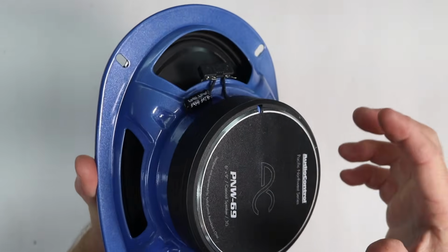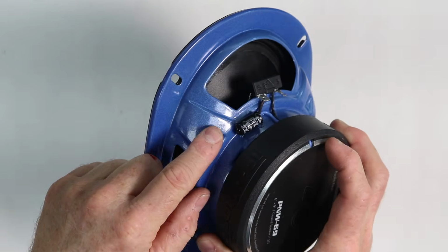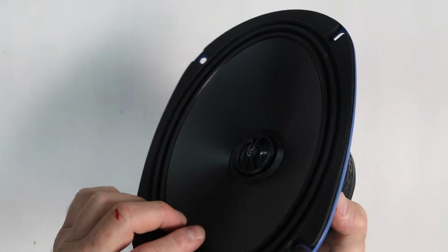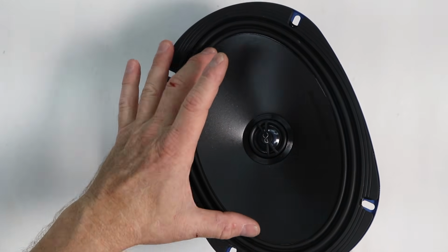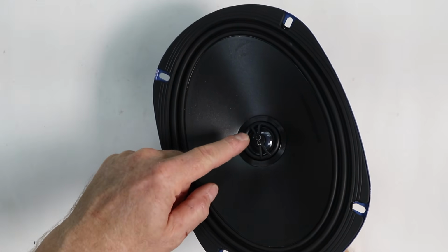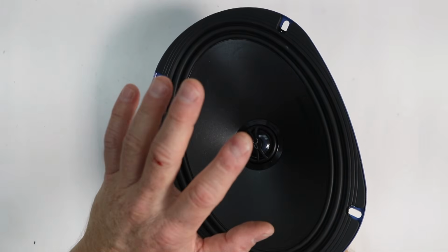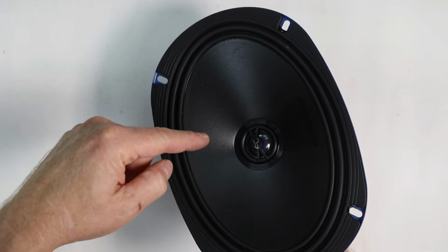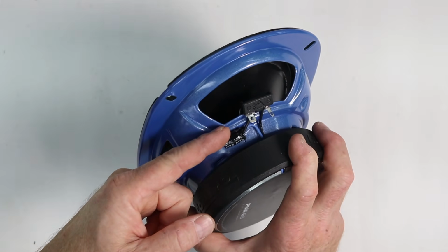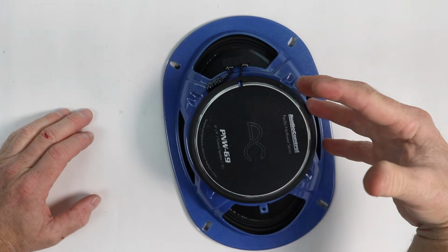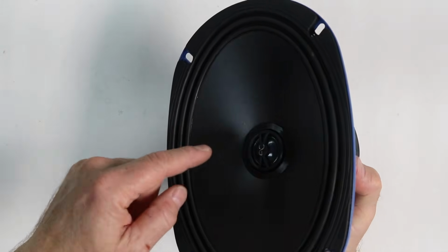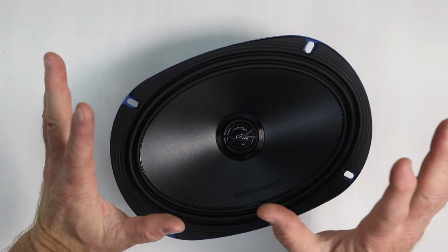It's a little tiny, almost looks like a battery. This is a capacitor. This is the bass blocker for that tweeter, because obviously this big mid bass can handle a lot more power and frequencies, it moves, and that tweeter, well, it doesn't do any of that. So we need some form of a traffic cop to limit the amount of frequencies that get to this tweeter. And a simple way to do that is with the capacitor, which is a high pass filter, but it is done passively. Amplifier power comes into the speaker, it goes through here, the capacitor blocks lower frequency from getting to this tweeter, and it is all done, and there is nothing to it.